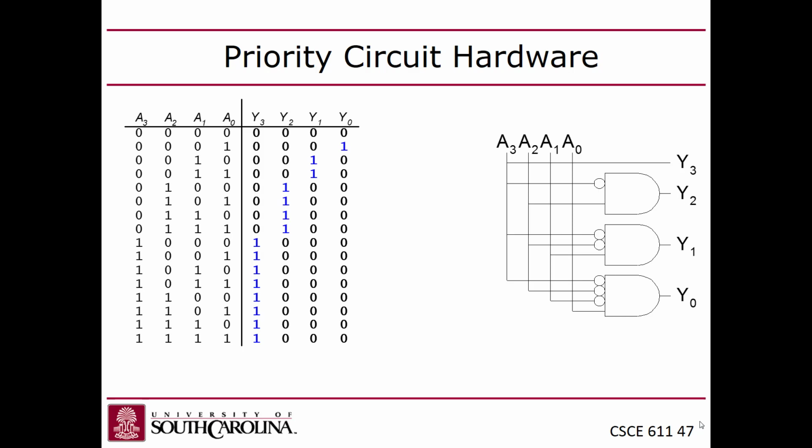So this one wire fans out to multiple places, right? Make sense? But you have to be careful that if you look at the output of a gate, each wire can only be driven by one gate output, can only be connected to one gate output.